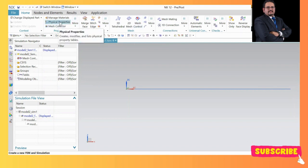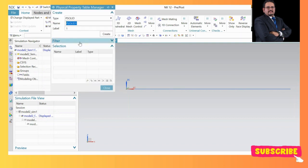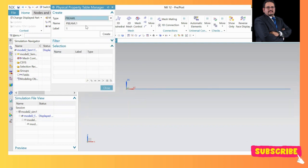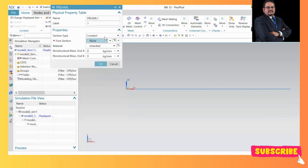I need to click on the physical properties first. Here, I would say what type of elements I need to work with, right? Now, if my object is 3D solid, I can work with this, P solid. The element type will be solid 1. If I am going to work with the beam element, for example, then beam properties should be there. So these are beam elements, right? These two can be used alternatively. I pick this one, then I say create. So I will create this one.